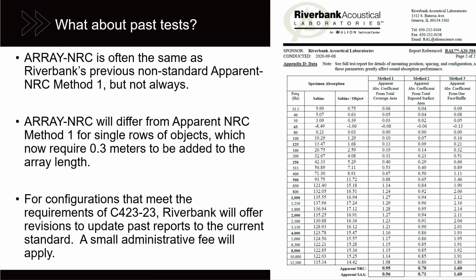And many of you that worked with me in the past, I'm usually helping you to figure out, is it type A mounting, is it type D, etc. And you may have heard me say a type J, or this is a type J. Well, type J actually has a specific configuration as the default, and this is 8 baffles that are each 24 inches by 48 inches and spaced 4 rows of 2 with 12 inches between objects in a row and rows 30 inches on center.